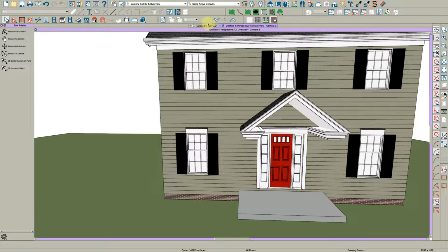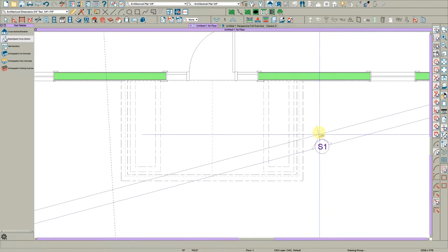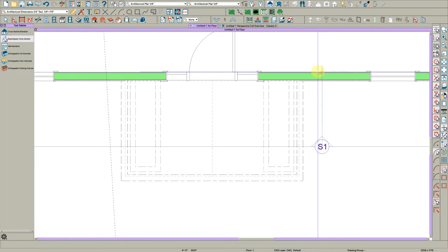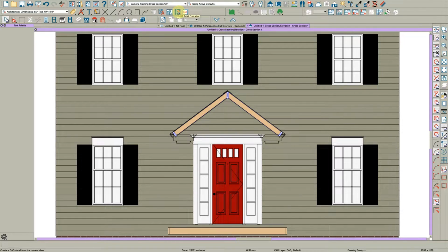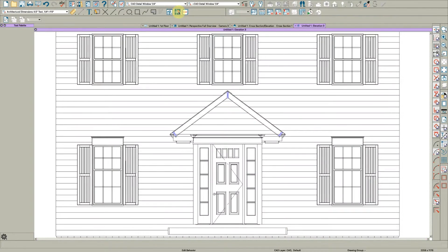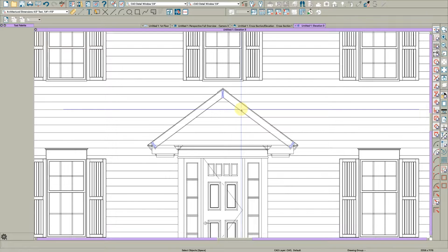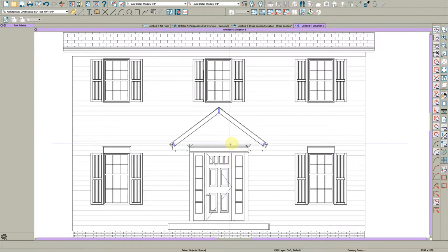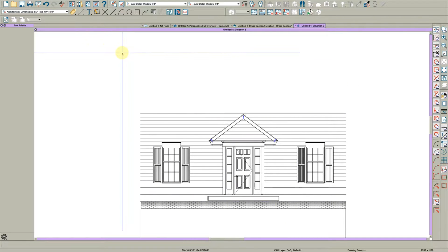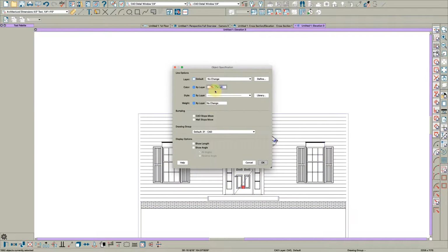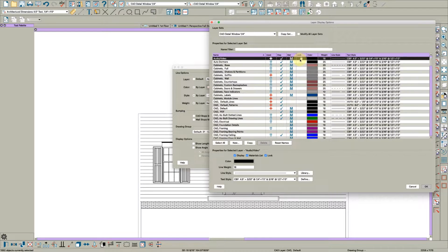So what we're going to do is take a section back clip. I have a hotkey for it, SB, so just so you know. And we are going to look at this, and then we are going to do up here, CAD detail from view. The reason I took it inside here is I wanted to be able to see this soffit. So the next thing I'm going to do is delete all these lines above here. I don't need them. Then I'm going to press Command A, open it, and put them all on the same layer, and make sure it's locked, and it is.